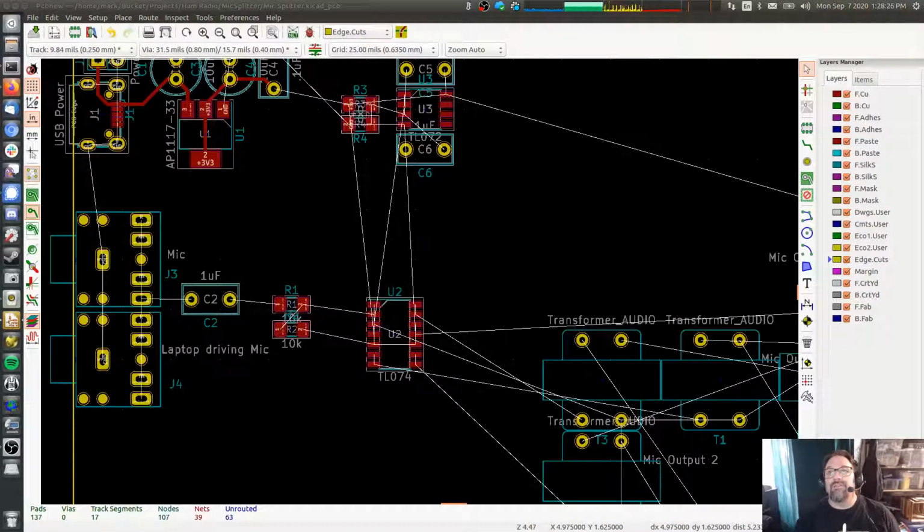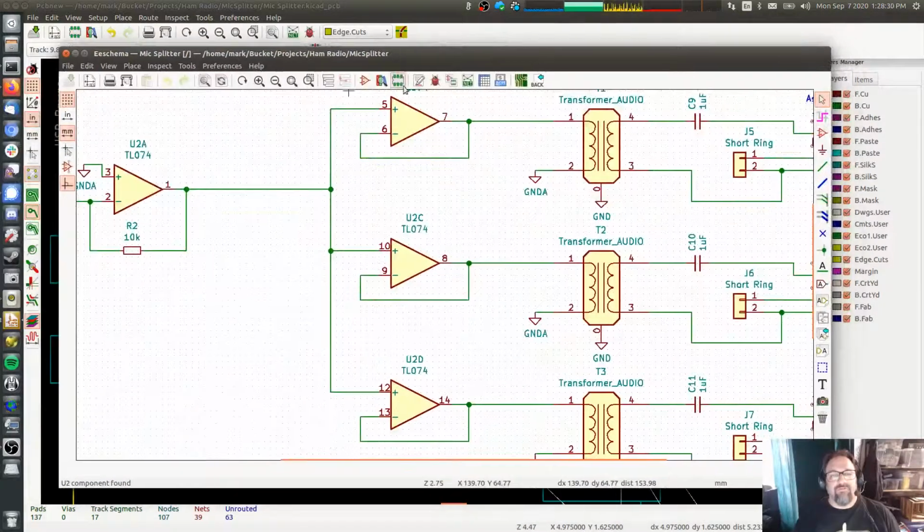And then those are all, yeah, see, normally when you have 4 op amps in a single chip, it's kind of hard to route traces in and out and everything. But these are all just shorts. So this is going to be super easy because that's all traces. There are no components.